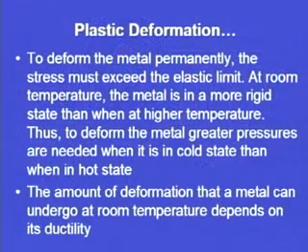It is easier to work a metal in a hot state, and more pressure is required when we are working with a metal in a cold state. The amount of deformation that a metal can undergo at room temperature depends upon its ductility.